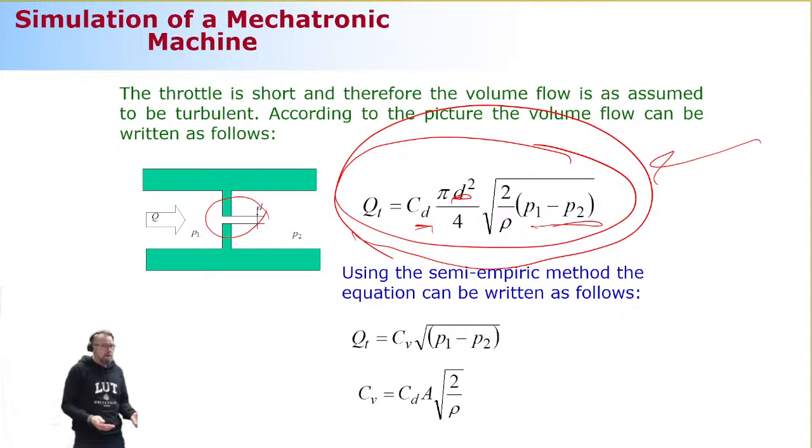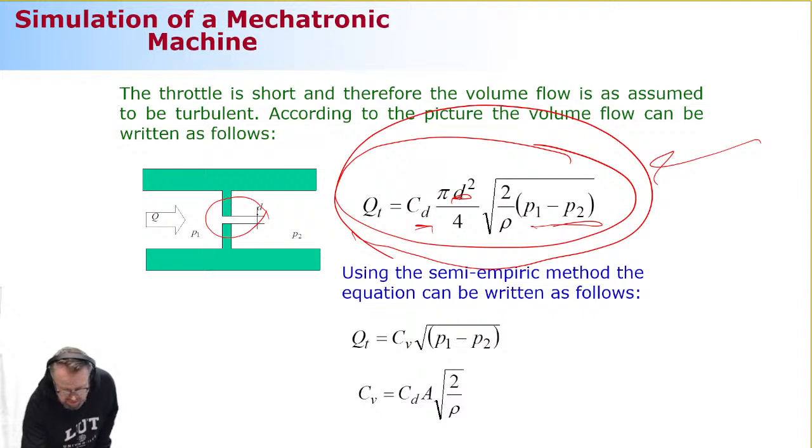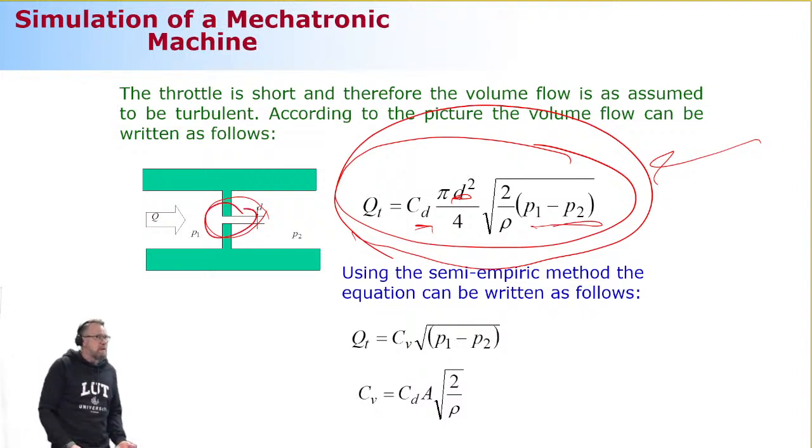So the measurements you need to do yourself are nothing. You just take a look at the components. This is the component that I like a lot; I think it is going to work well in my hydraulic circuit. And then you look at the manufacturer's catalog. What are the parameters? What are the characteristic curves? Based on this information, you're able to create an equation describing your particular component. What it means in the case of the throttle valve is this. Parameters that seem simple to get, like the diameter of the throttle, might be hard to get in real life, but you can get the characteristic curve. You can see how it behaves as a function of the pressure difference, and based on that you can see if it is a turbulent or laminar flow. Most probably it's going to be a turbulent flow.